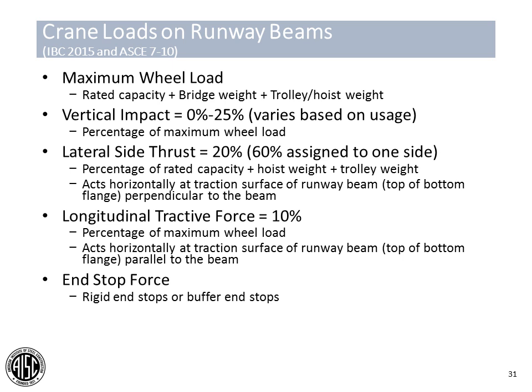Impact forces, like we discussed, include the vertical impact, which ranges anywhere from 0 to 25% of the maximum wheel load. This varies based on the usage of the crane. If you have a manual bridge crane system, which in this instance would be pretty rare, you actually have a 0% vertical impact factor due to the slow motion of the crane system. And it ranges anywhere up to 25% for a pendant operated or a cab operated structure.